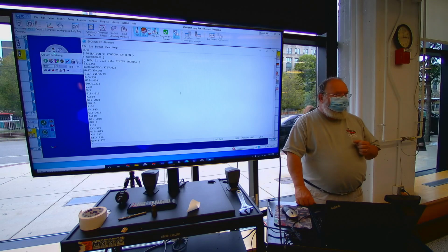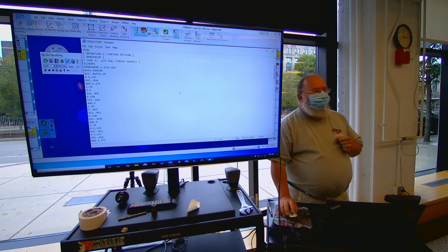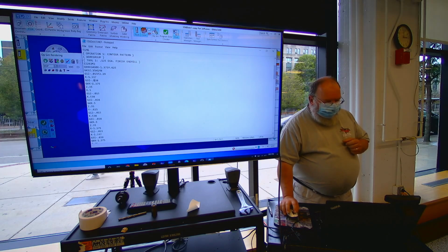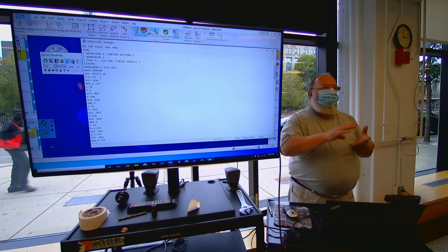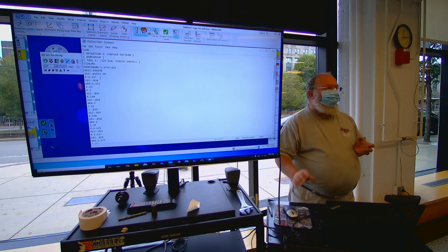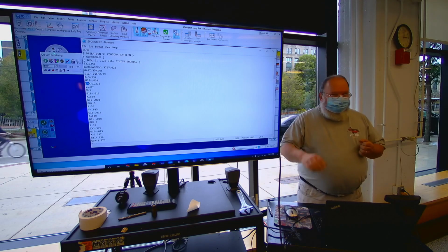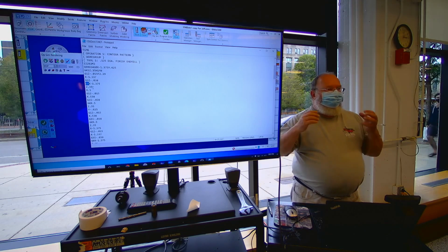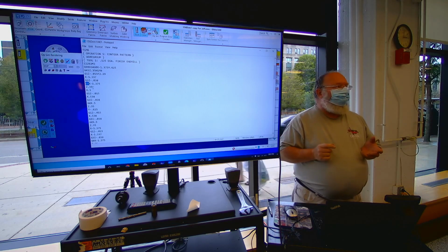All right? This is called G code. This is what the machine reads. It's not nearly as complex as it looks. There's 4 basic codes. Depending on which axes you use them in, you can machine anything you can imagine. I'm going to start off with the first one, which is G0. G0 tells my machine from where you are to where I want you to wind up as fast as you can get there. It's a rapid traverse command. It's that 1,000 inches per minute.